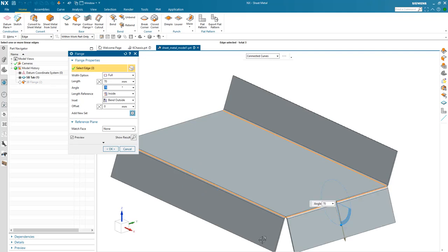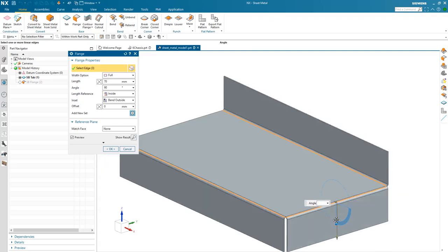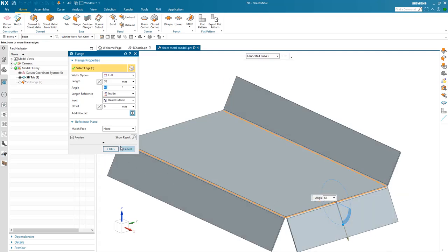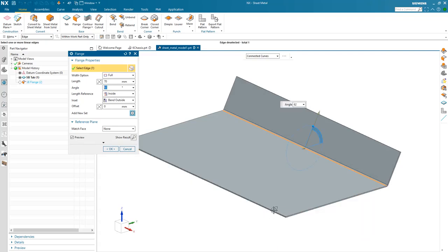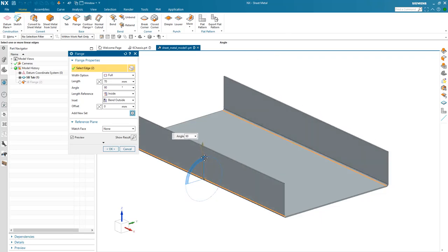So now as we select a handle, we will see how the flange is moved dynamically to the location or the angle that we want. But once again, we want to do a shift select. What we really want is just one single flange on the opposite end. As we rotate that to 90 degrees, where we have the length of 70, that is set.